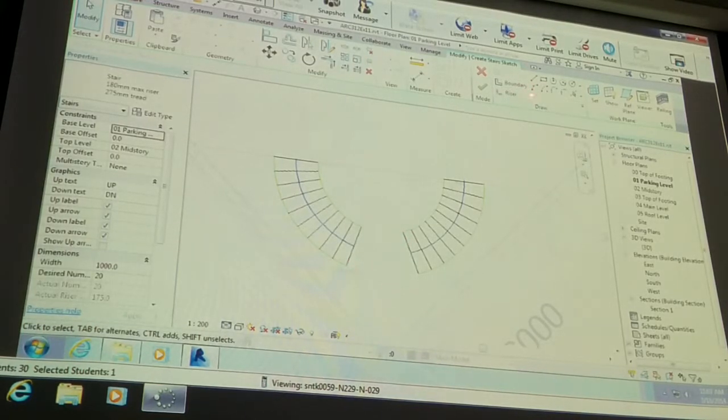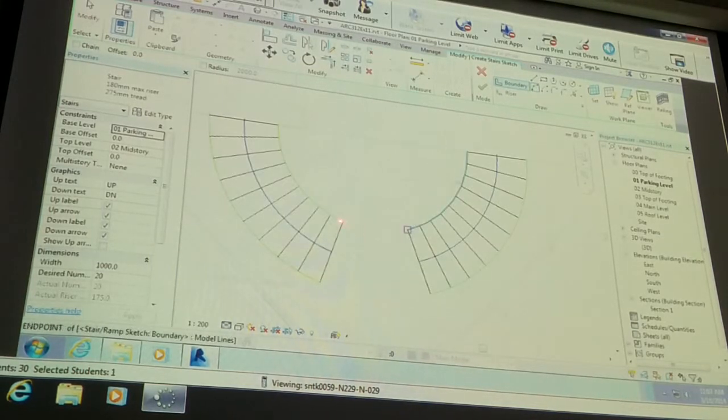So now I would use the 3-point arc tool, it's probably easiest. So if you go from end point to end point, and normally I'd go from left to right, but it probably doesn't matter. But no, you want this arc to be the same radius as these 2 sides, right?